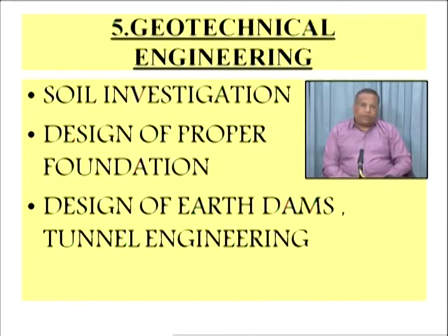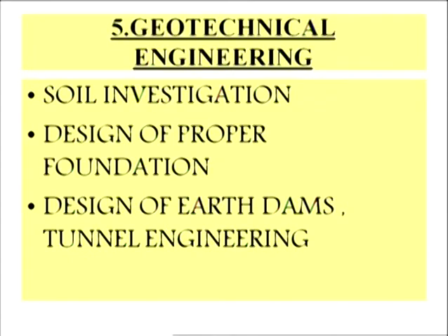One important task to be done in this branch is the soil investigation. Different types of soil strata are to be investigated. Their soil parameters are to be measured, like their density, their porosity, their cohesion. Different types of soil parameters are to be measured in the soil investigation. Safe bearing capacity is also measured. On the basis of the safe bearing capacity, the design of the proper foundation is to be carried out.